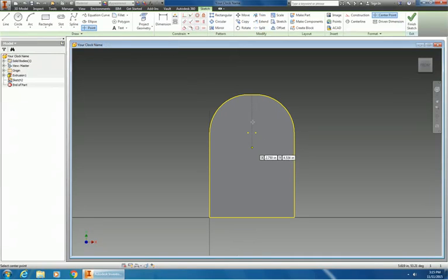Now if you roll in just a little bit, this will actually select the dead center of your piece, so that already centers it out for us. And you can place that point anywhere down on the part, because we're going to dimension it here. We're going to dimension a distance from the top of this part to the point, which is 3.5 inches. That's our dead center.